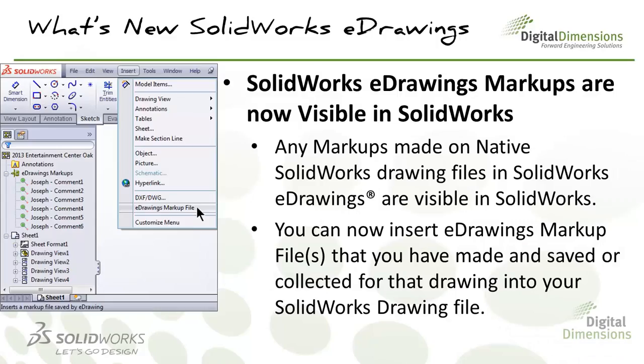And the next item on the agenda is the ability to save eDrawing markups when opening a native SolidWorks drawing file. So in other words, from eDrawings, if you manage to get a hold of and open the native SolidWorks drawing file, add some markups to that drawing file, when you save it, the next time that SolidWorks drawing is opened in SolidWorks, those eDrawing markups will now show up in your drawing file.